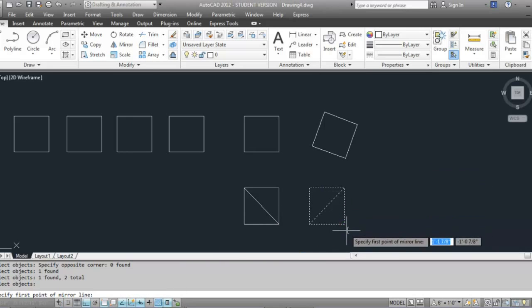If you hover your mouse along the corner of this box here, and when it identifies the end point as the object snap, you can slowly drag your mouse, and you see the green line. That green line is tracking that end point along a perfect horizontal axis. So it's letting you use the end point as a reference point, and it's tracking it across, so you can use that exact same point for your mirror axis.